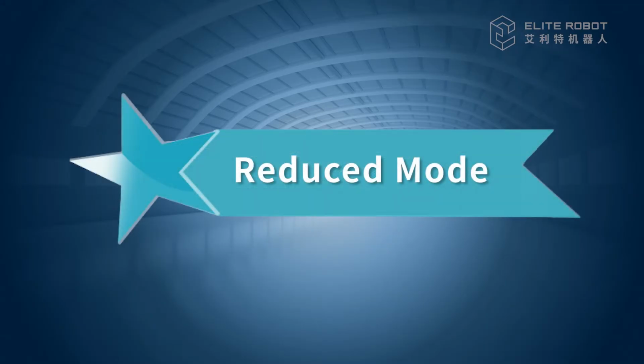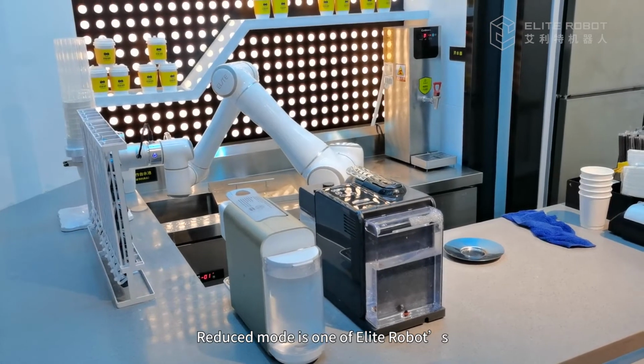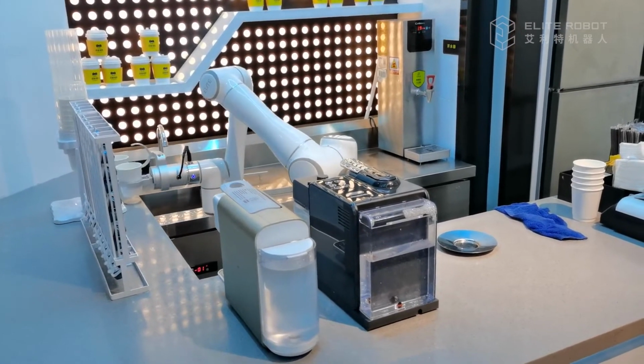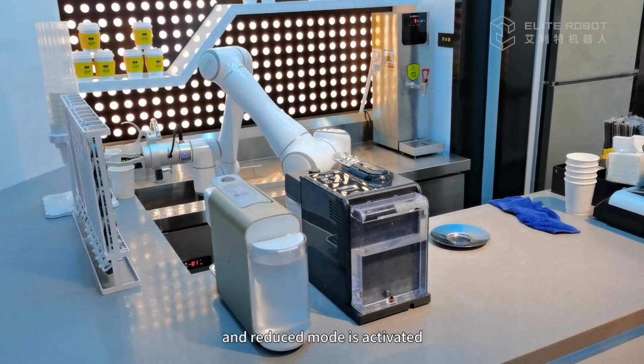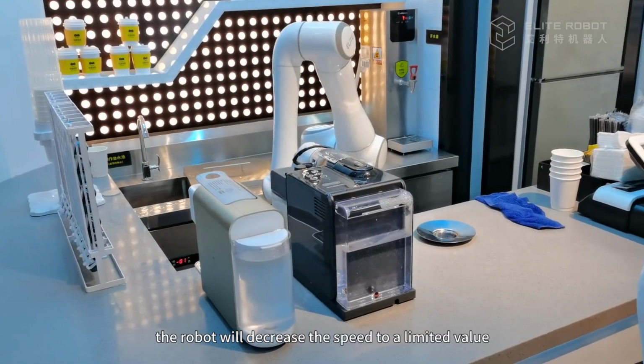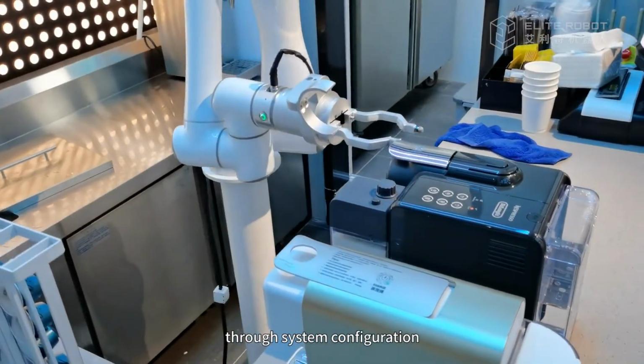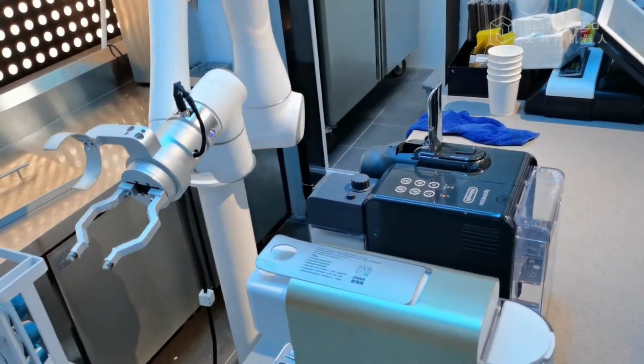Reduced mode. Reduced mode is one of Elite Robot's safety functions. When the robot is running and reduced mode is activated, the robot will decrease the speed to a limited value. This speed limit can be set through system configuration.